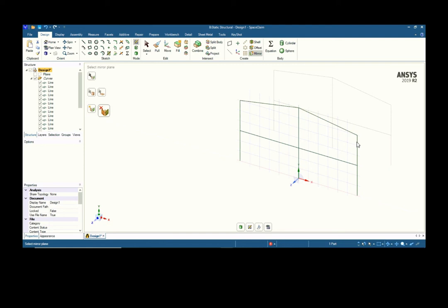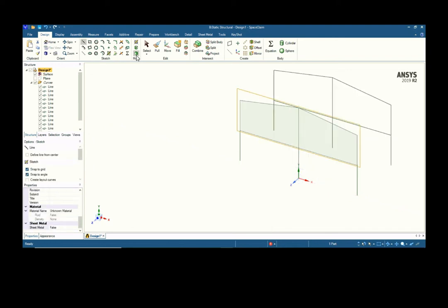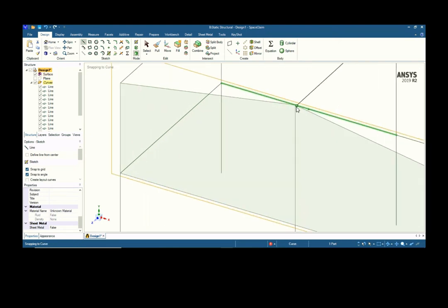Then we have to create lines for connecting these two bodies. So you select the line, then put it in 3D mode, and you can draw the lines, connecting this line to this line. Then you click escape, and connect again after you have done that particular line. Click escape, then here again to here, and zoom in a little bit.